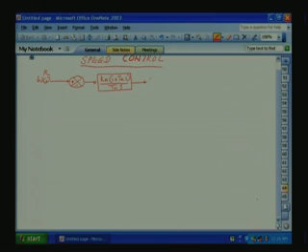Now this will give the current reference, and the approximate current transfer function which we can use in the speed loop is 1 by 1 plus 2 sigma S. The sigma we know, it is the sum of the smaller time constants, that is the converter lag and the current filter time constant. This will give to the machine.